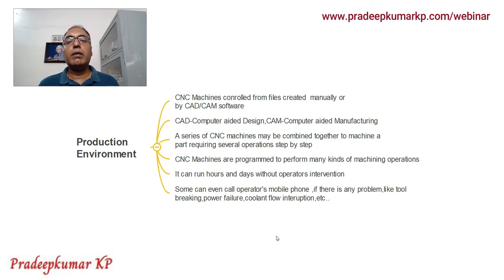That is, the CAD becomes the basis of the CAM programming. Looking at the digital content of the CAD, whatever information is in the CAD will be taken for the CAM programming, and we also give additional information, like the way we have to operate and the kind of operations we have to do, like milling, turning, deep engraving, marking.